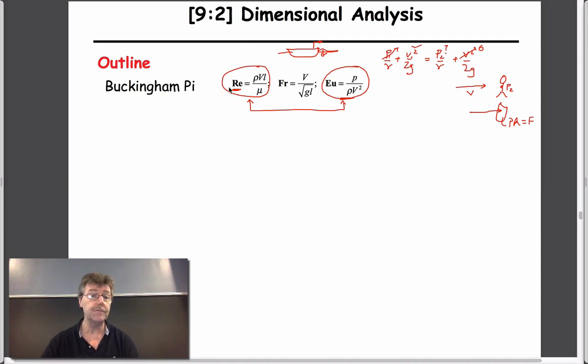So what we'll do today is we pulled these out of a hat kind of last time. You remember that we derived these based on Bernoulli's equation. Pressure term, velocity term, elevation term or gravity term, and also a viscous loss term. And from those four terms we got all of these expressions. We did that last time. And so that's where they come from. The question now is, how do we define the appropriate dimensionless groups that will describe a particular behavior for a system we're interested in?